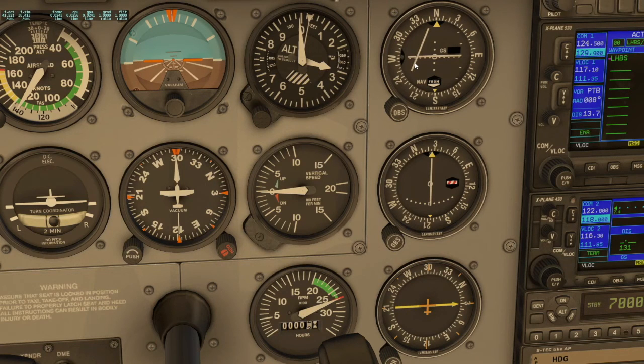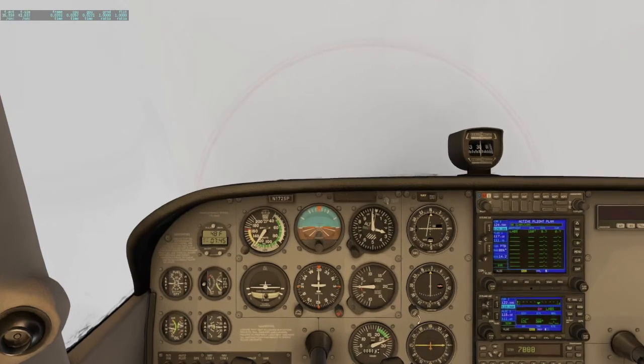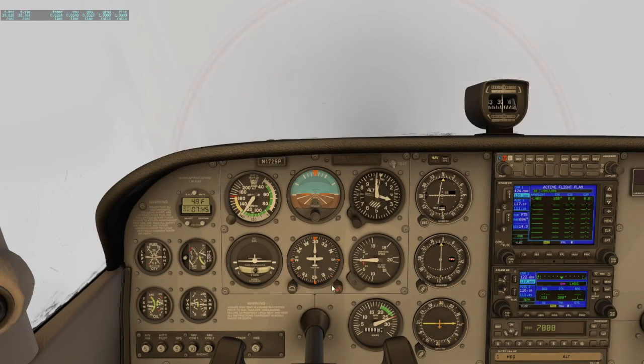The needle is moving closer, as you can see. Very good. That's what I was expecting. That means we're approaching the radial. We're almost 5 degrees away. Now we're closing into 4 degrees. So I'm going to turn to 210. Time to turn now to 210 so we can catch this radial. Here we go. Now I'm turning to 210.